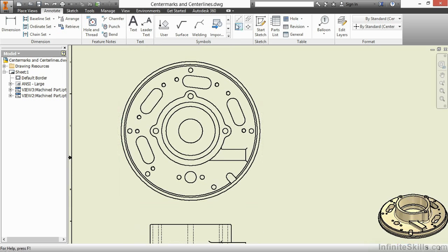Next up, we'll look at the center line and center line bisector. These 2 commands are very similar to each other, and a lot of people use them inappropriately. Let's begin with the center line tool. The center line tool is designed to go across large center lines. So as an example, maybe I will select right here on this circle, all the way down to this circle, right-click and choose Create. And then here, I can extend that beyond to another circle here.